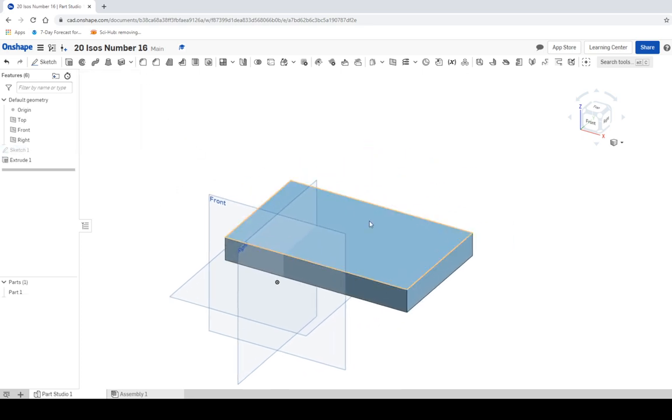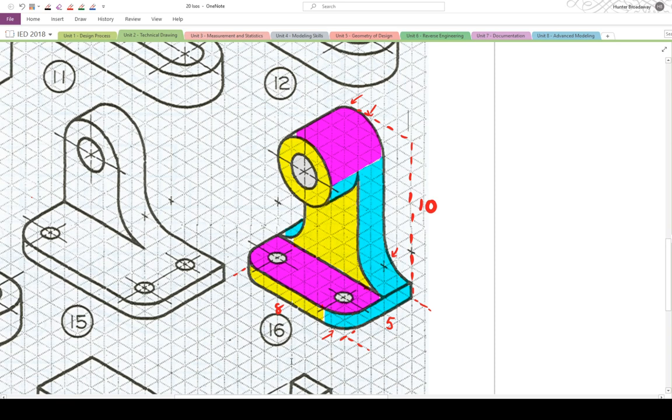Okay, from there, let's get a block out on the side, and let's use that block to expand it outwards. This block is going to be 1, 2 units in, and 1, 2 units in, and this block is also going to be 1, 2, 3, 4 units thick. So we're going to be making a 4 by 2 rectangle, and then we're going to extrude it up 9 inches.